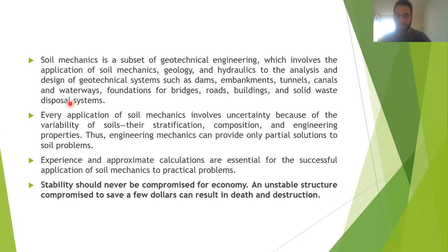And the most important thing, the one that investors hate, is that stability should never be compromised for economy. You cannot save on investigations. You cannot save on designs. In general, depending on what structure you are building, the geotechnical investigations should cover around 1% of the whole budget for a building. For more complex structures, like tunnels and especially dams, it should be like 5%. So you should never compromise stability for economy.